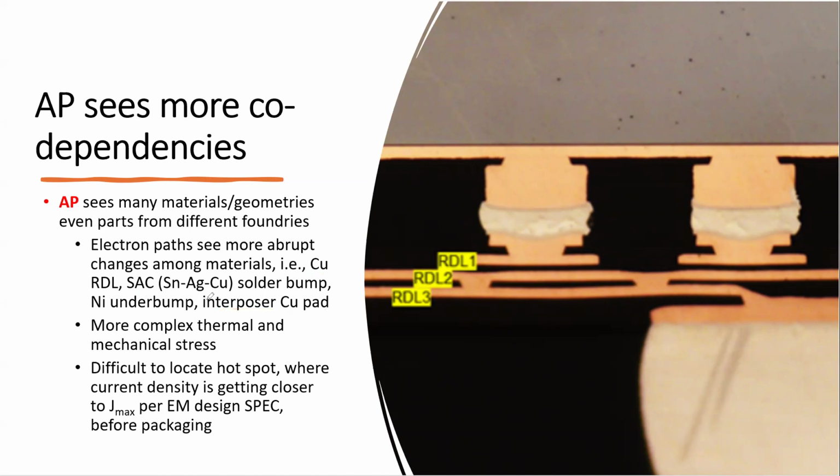So all these are different materials, with different thermal expansion coefficients, and different resistance, by the way. And then the shape and thermal, they're all very different. So you have different thermal stress and mechanical stress because the way they are manufactured is different. And they'll see different environments. Of course, you have different stress.